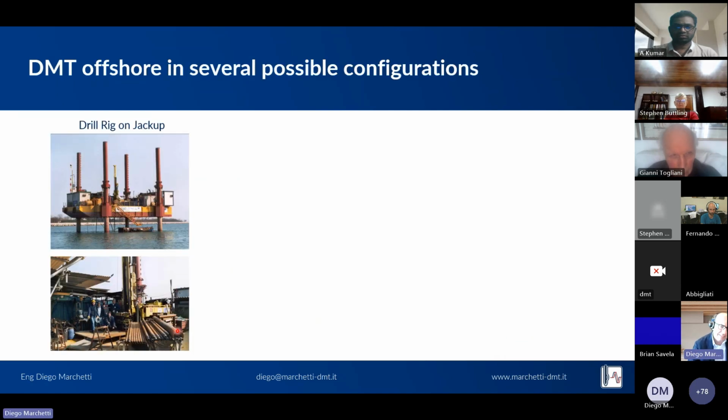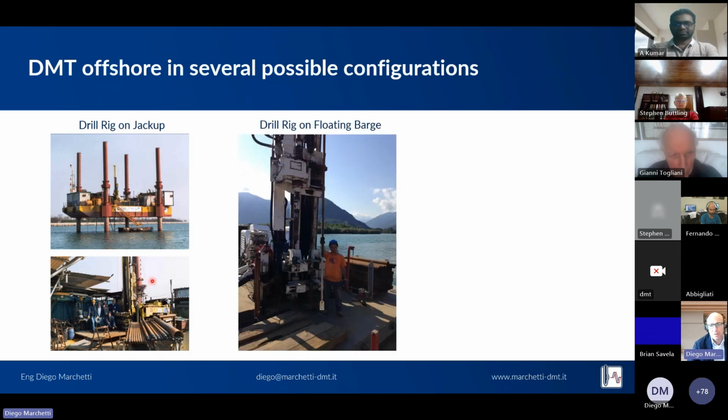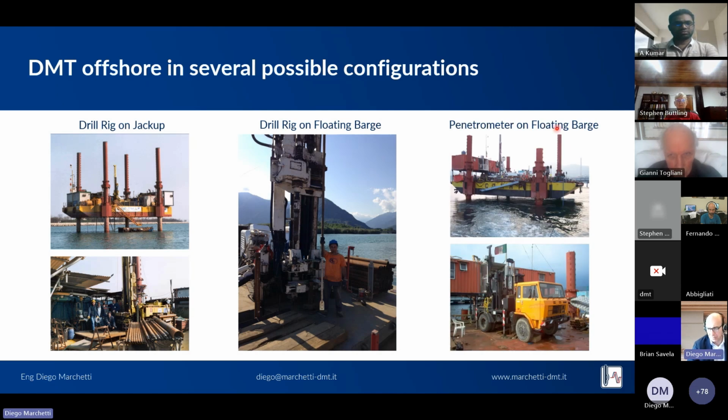Now, the test can be performed also offshore, either from a jackup using, for example, a drill rig, like in this project of Venice for the mobile barriers, or in this case, a lake from a floating barge using a drill rig, or with a penetrometer on a floating barge. Any configuration is possible.